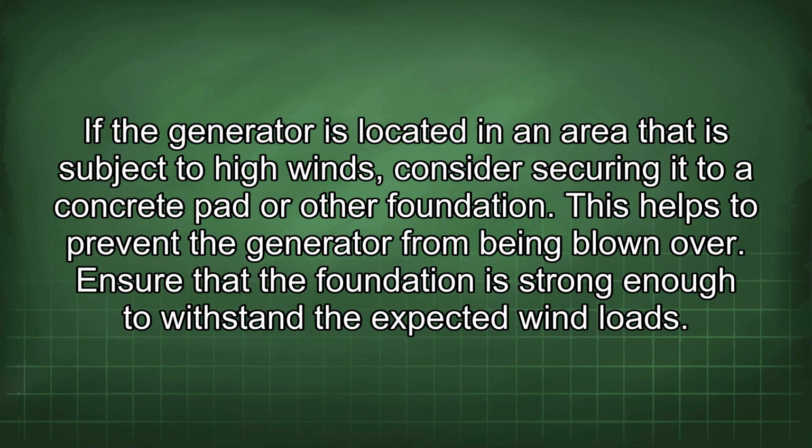If the generator is located in an area that is subject to high winds, consider securing it to a concrete pad or other foundation. This helps to prevent the generator from being blown over. Ensure that the foundation is strong enough to withstand the expected wind loads.